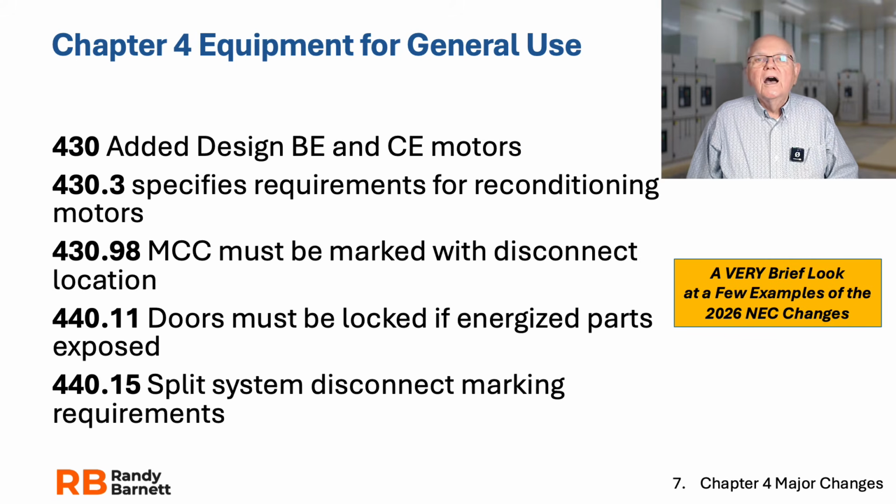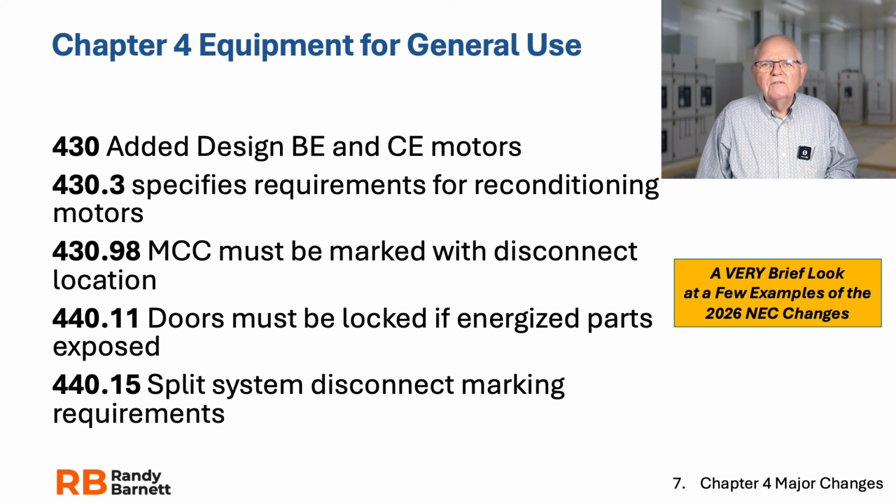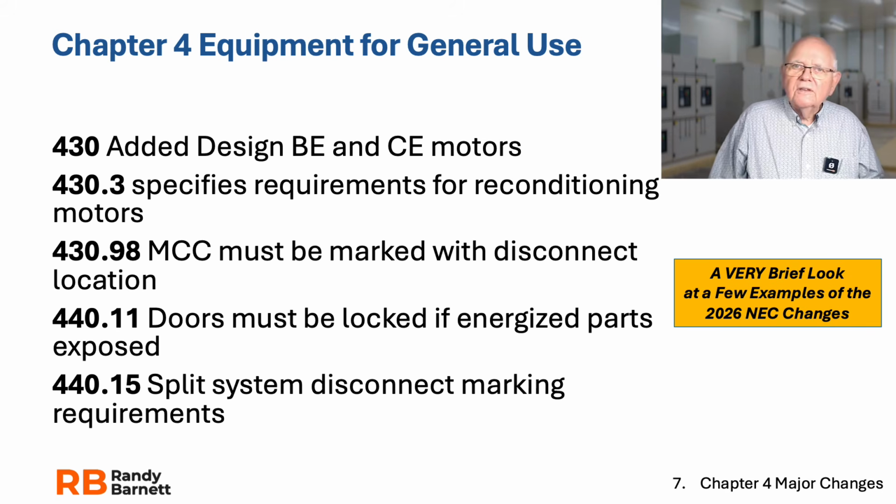430.98, MCCs, motor control centers, must be marked with the disconnect location to de-energize all the power to the MCC. That's a good safety thing. I've got to lock out, tag out this MCC. We've got to get in the back and do some work on the bus work or whatever it is. I want to make sure I get all my sources of power. Good way to start, look at the front of that equipment, look at the labels, and find out where all your disconnects are located, what's supplying power to that MCC. It could be more than just that 480 coming in.